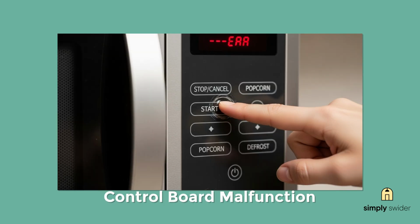If you've tried everything and that PF code just won't go away, or your buttons aren't responding properly, you're probably dealing with a faulty control board. The control board is basically the brain of your microwave. It processes all your button presses and manages the heating, lighting, turntable, the whole show. When it goes bad, you'll see persistent error codes or completely unresponsive buttons.